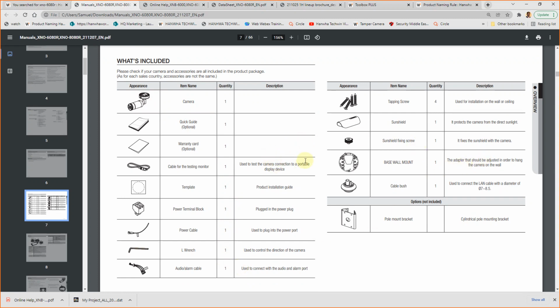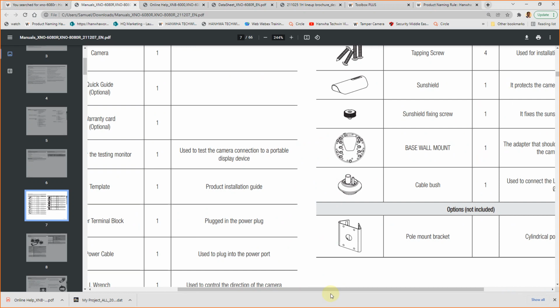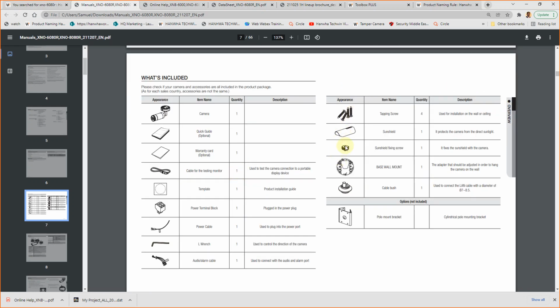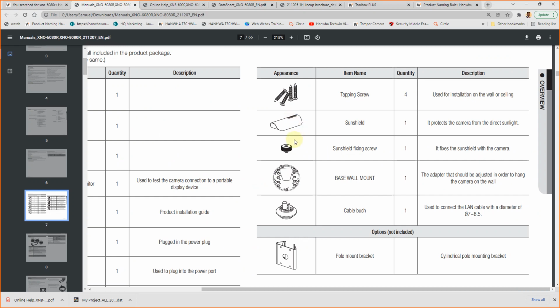All right. What are some of the key points which are usually thrown away, trashed, because whoever is opening may not know it is useful? IP66 protection, waterproof cable bush. It looks like a rubber piece, but it's for waterproofing. All right. This small screw is to fix the sun shield. If you miss the screw, you need to buy or put some other screw.